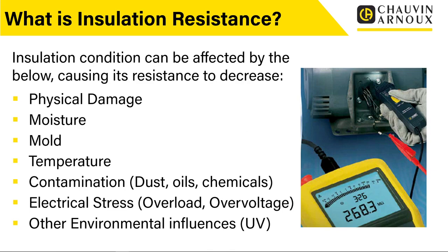So it is very important when we're looking at our cables and at the form of insulation we've used to make sure that that insulation is suitable for the job in that environment. And this is why when we do insulation resistance testing, we're monitoring to make sure that these effects haven't become too severe, to the point where the insulation is damaged and is going to start leaking current through, or start failing. And then obviously that could become dangerous, or the equipment could stop working.